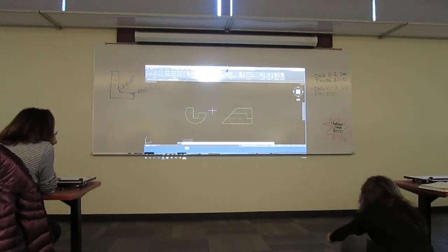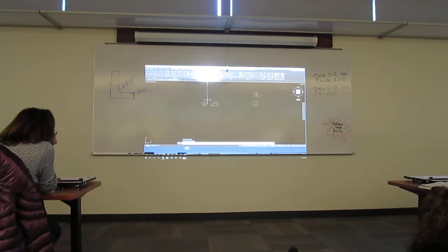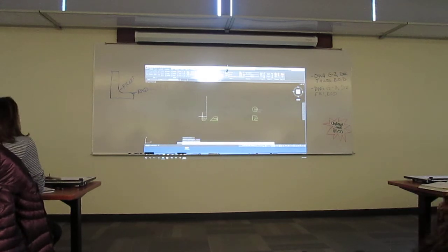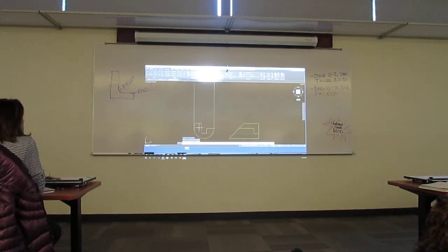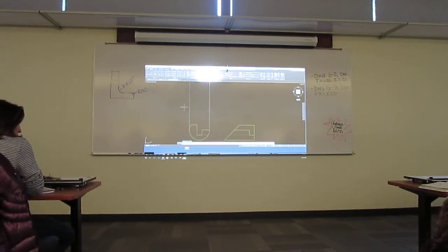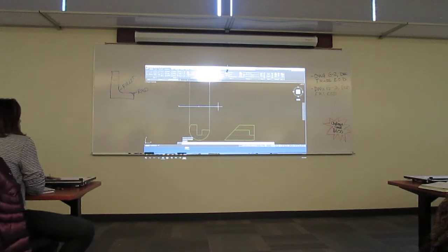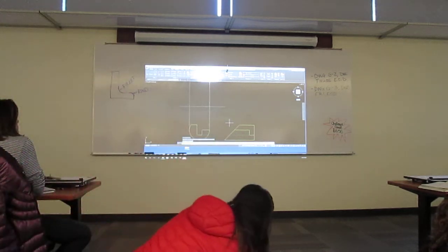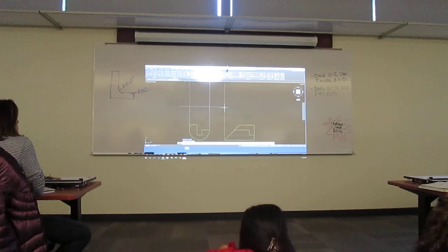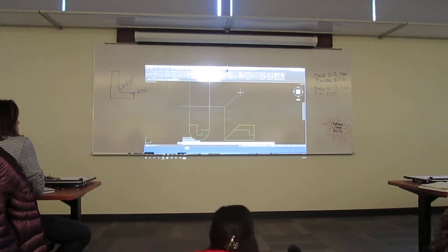So the first thing I'm basically going to do is take my limiting elements, throw them up so I define my width that is going on here. Now, once I do that, I need to define where my depth occurs. I could use a phantom line. I'm just going to use the object itself. So I'm just going to throw an arbitrary line out. That will be the bottom. I'll use that to create my miter line. So my miter line will then go from there to there and then go at 45 degrees.